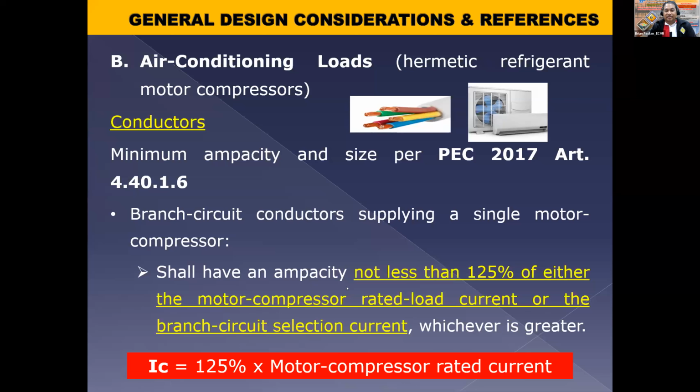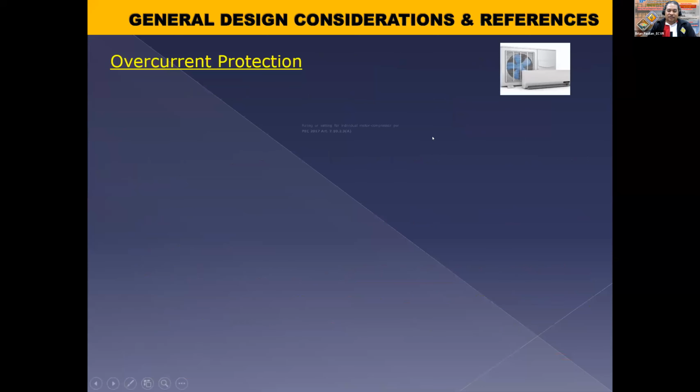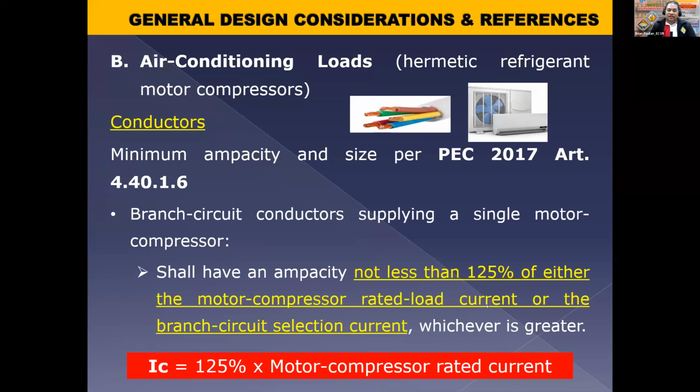Okay. Yeah, tama po, Sir Regidor, no? FLC is from the PEC table. Okay? So with that being said, let's proceed. So again, 125% of the motor, either FLC, no? Or yung whichever is greater, okay?